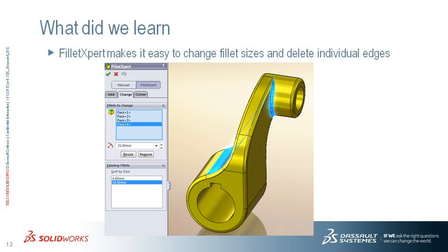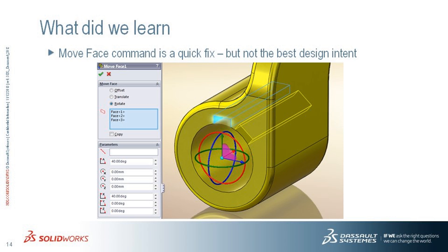Fillet expert, again, like I said, using the delete option and the resize option are both great tools. And then finally, move face. Move face, you could argue, hey, that's probably not the best modeling technique. You should probably go in there and sketch it out properly. I agree, 100% agree. But this is a contest. We're trying to get things done.